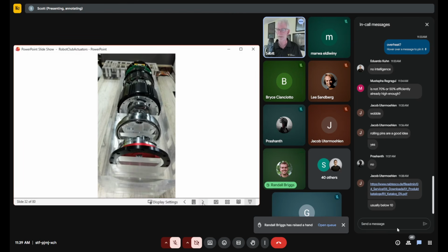Yes, Randall. Hi, I had two things. One was just a quick comment on the strain wave gears, that I think is important for people to know, because I didn't know this until recently too. On the one hand, they say that they have zero backlash, but the problem is the cup of that spline is really flexible, right? It has to be to do the bending. And because of that, it's not very torsionally stiff. So even though there's quote unquote no backlash, the output is somewhat weakly coupled to the input. So there is some flexibility there, even if it's not purely backlash. Yes. Yes.